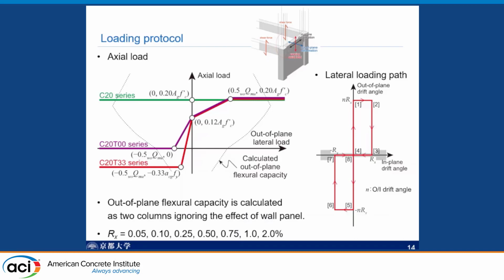And then there are some ways to apply lateral loading, so we have to decide how we apply the load. This is the way we apply the load. This is the starting point, and first we apply the out-of-plane loading up to this point, and then we apply the in-plane load.